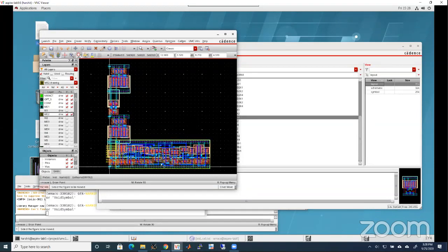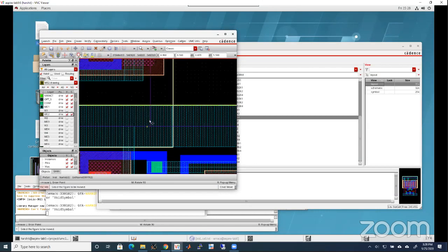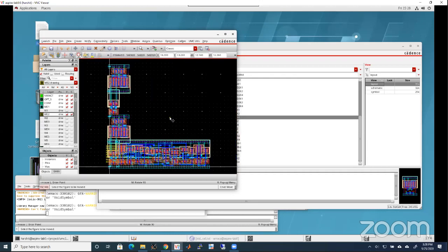The height of the standard cell stays the same for all the gates. You cannot change the height. Therefore, the standard cell grows in the X direction. When you have to stack standard cells, you have to stack them so that you do not have any spacing. So I have overlapped the VDD, I have flipped it and connected it.